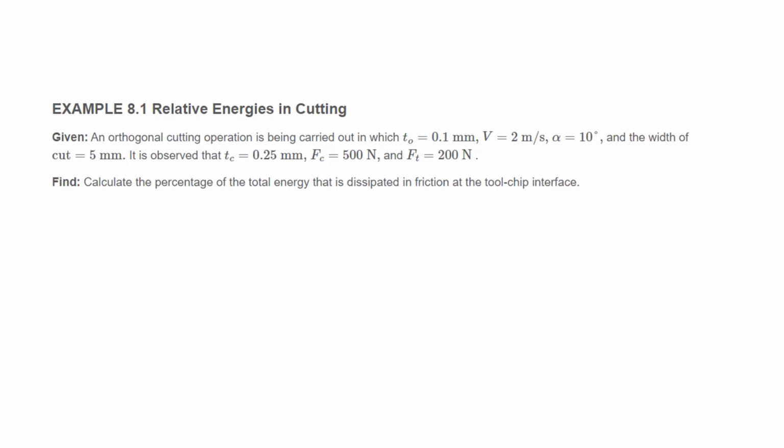After I calculate beta, my R is known, so I can plug in. F equals R, 538 Newton, multiplied by sine beta. So this F turns out to be 283 Newton.